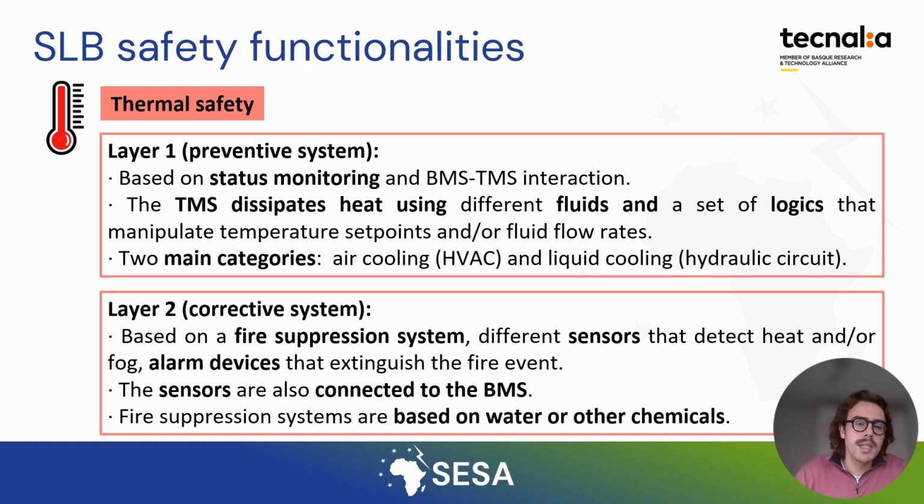The thermal management system's goal is to dissipate the heat from the battery using different types of fluids and a set of logics that are used to adapt these set point temperatures and the flow rates of the cooling fluid. Nowadays, there are two main categories of thermal management systems. Air cooling systems, mainly based on HVACs and fans, and also the liquid cooling systems made of hydraulic systems with pumps, channels, and heat exchangers.